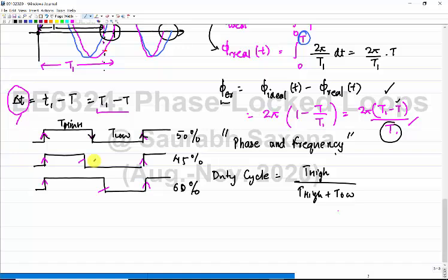Few events are coming at a faster rate as compared to the other events. Similarly, it will be slower for the other cases. So yes, it is true for synchronization. We may generate a low frequency clock and use both the edges to synchronize our events, but in that case we have to make sure that we have this 50% duty cycle. If we don't have that, if we have like 45 or 60, we may have some trouble unnecessarily.